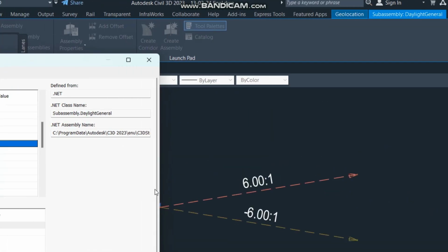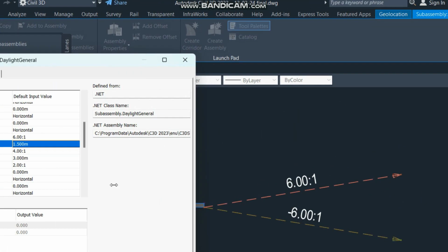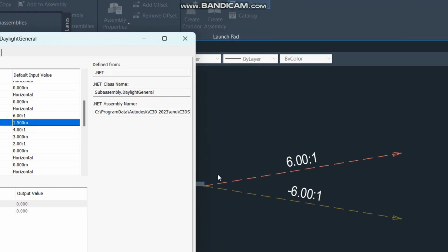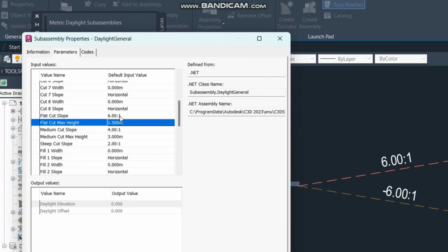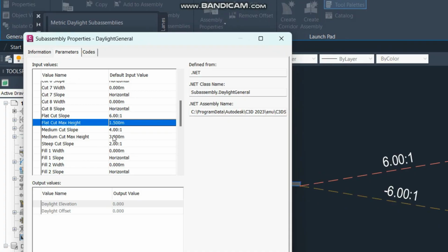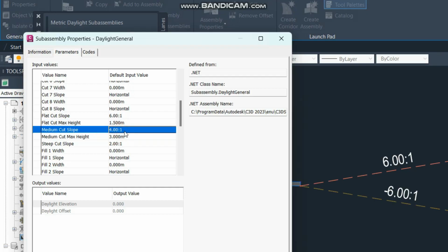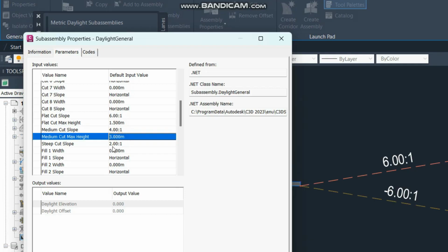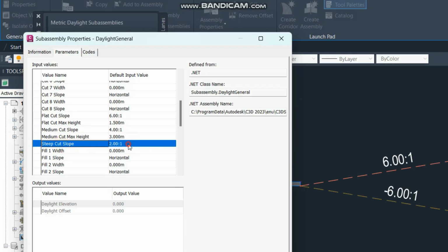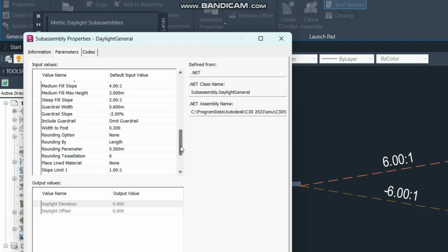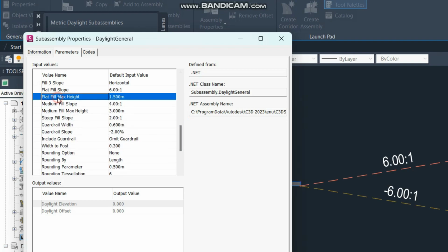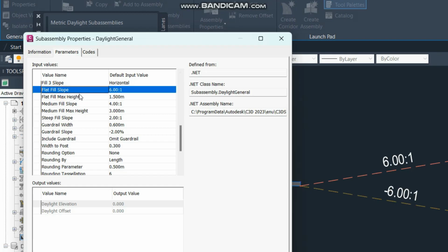If you go to the property, you will see this right of way limit, offset or alignment. Here you can assign to your assembly the alignment or the right of way limit, so it will target that place. It will not go outside this length. And the right of way limit offset is the distance you can give, so from that point it will not extend.